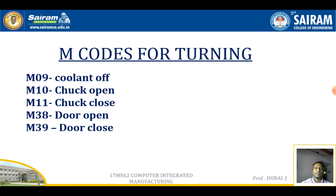Then M10, chuck open. That means while the chuck is opening, we can fix the workpiece or remove the workpiece. And if you want to fix the workpiece manually or automatically, that is also possible. This is the use of the M10 command.